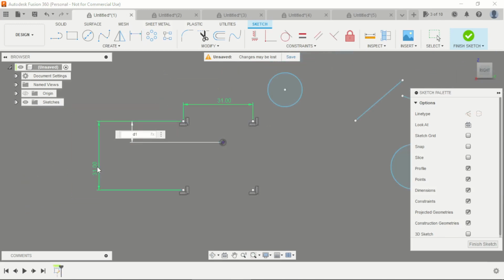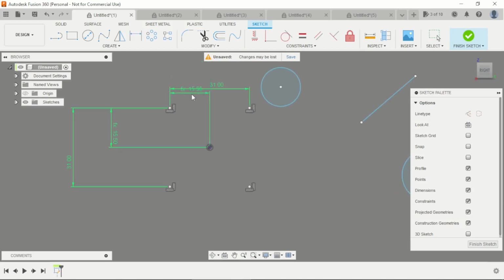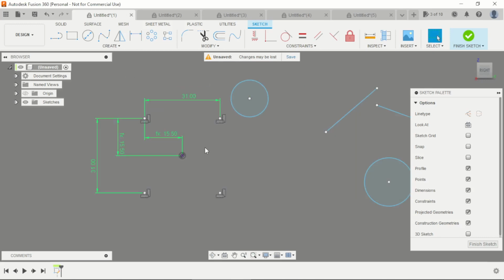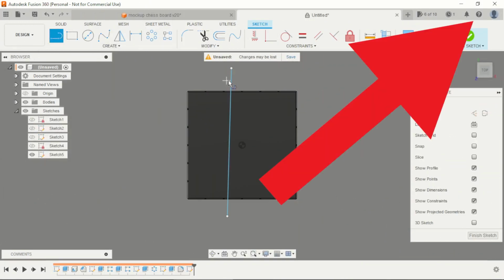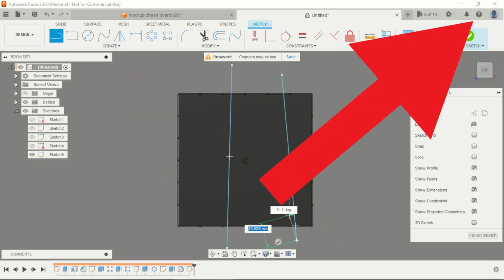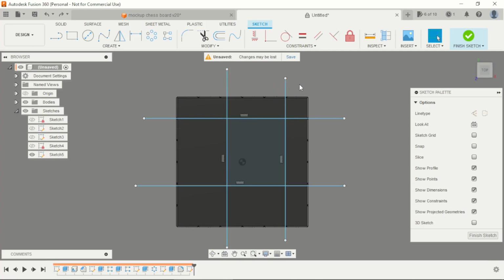Create another one, select first, divide by 2, and another, select the dimension, divide by 2. I made that in that video. That is easier to constrain points on the vertical and horizontal. In another video that I made, the chess board, I create a relationship between lines. Clicking on the lines that I have created, I apply a horizontal and vertical relationship. That is the most common use for this tool.